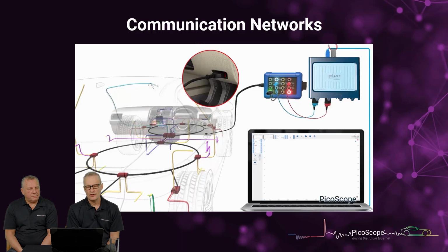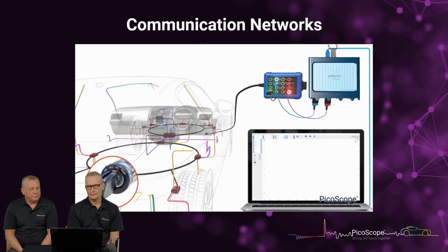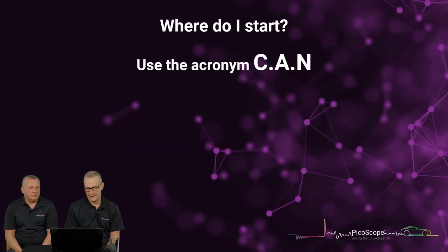So again, it's not always possible to get CAN data directly over diagnostic. It may be that you need to use our breakout box and link to the networks via the scan tool. So you're actually communicating over CAN with the diagnostic interface, the gateway, if you like, between the OBD and all those networks on the vehicle. With earlier vehicles, quite possibly you'll be straight on the network at the OBD connector, but it's one to be aware of.